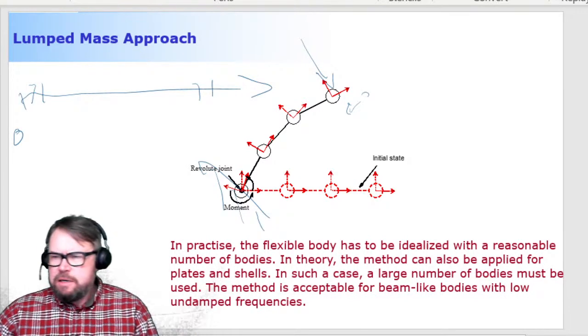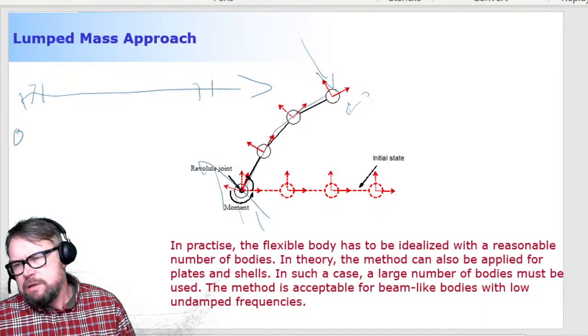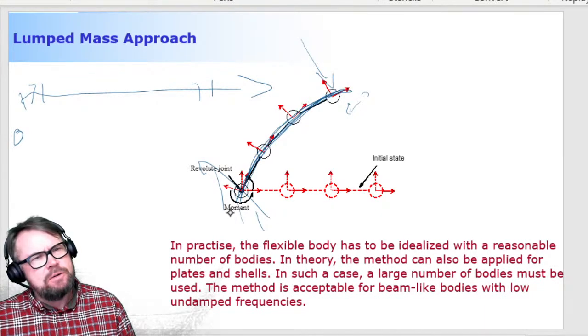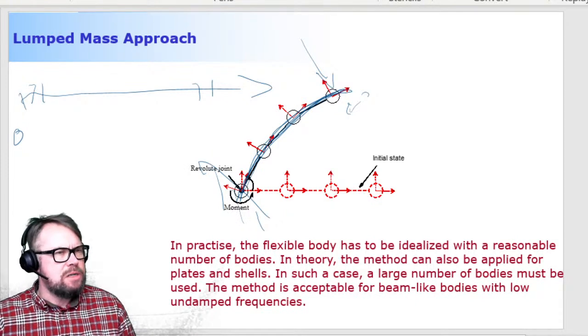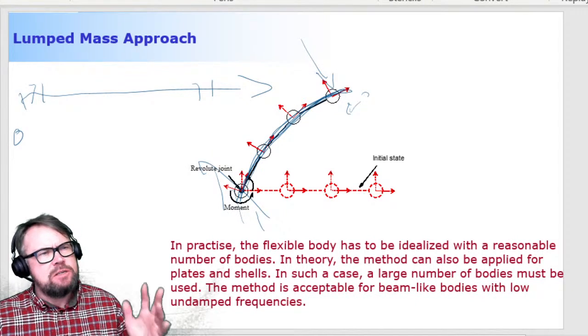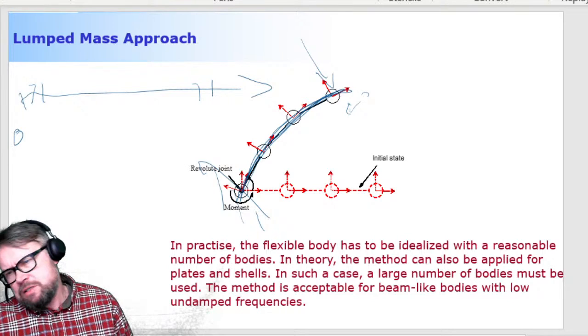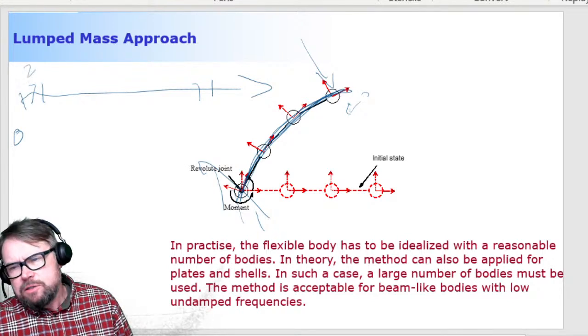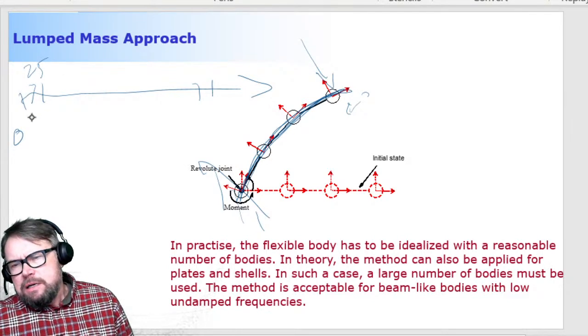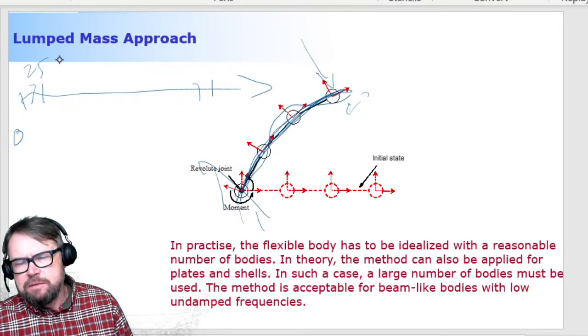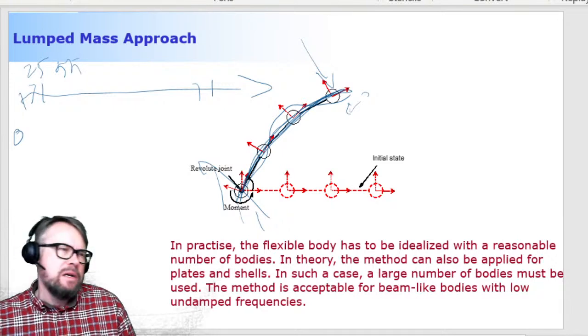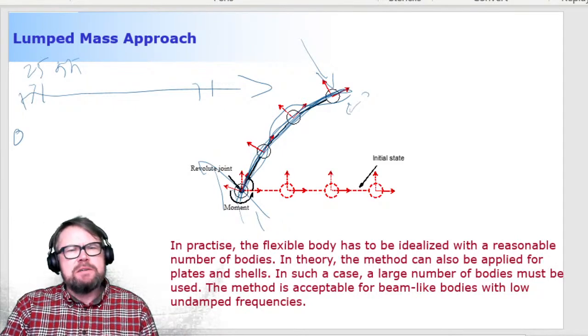Well, this beam structure is a good example, because the beam structure can have a bending deformation like shown here. The frequency associated with bending deformation is typically very low. Let's say it's like 25 hertz. Maybe there's another bending mode as well, like this, so it may be 55 hertz, which are considered low frequencies.